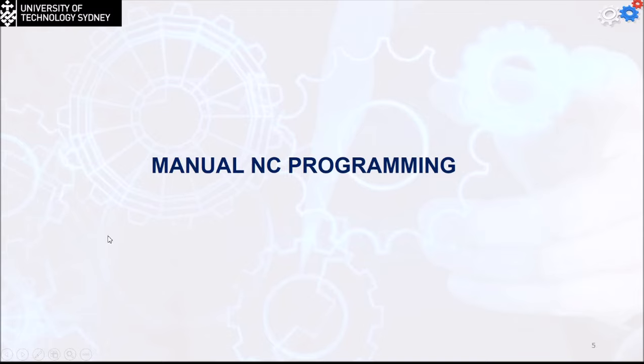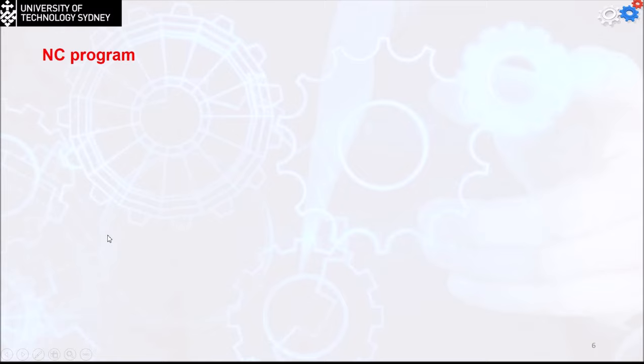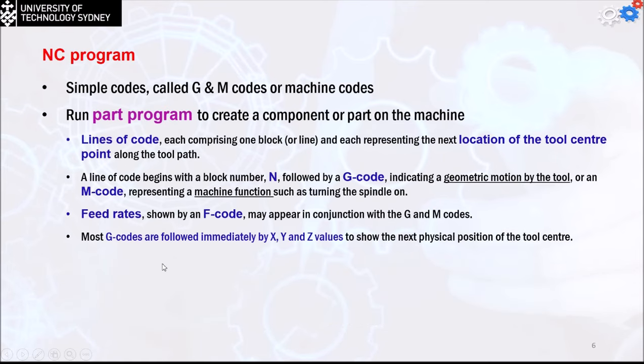So for manual numerical control programming, which is what we have to do in this assignment, we have to learn about the simple codes, called the G&M codes or the machine codes. We have to run the part program to create the component on the machine, and we are going to have lines of code, each comprising one block or line, and each representing the next location of the tool center point along the tool path.